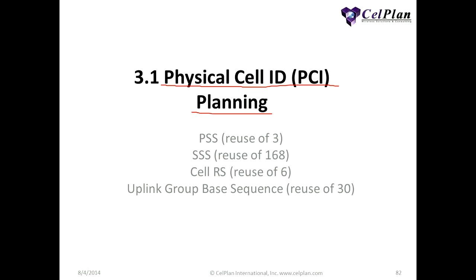And yes, it does reduce PAPR by a few dBs, 3-4 dBs, but it creates a distortion of 3-4 dBs. So there was not really a gain there, but there was a loss, and the loss is